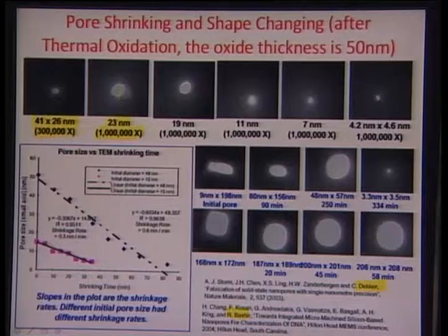And then if you look at the pore with time, as you are focusing the electron beam, the oxide reflows and the pore starts becoming smaller and smaller. So, it starts self closing till it attains about 4.2 nanometers by 4.6 nanometers, and you essentially stop the visualization process in this particular instance.